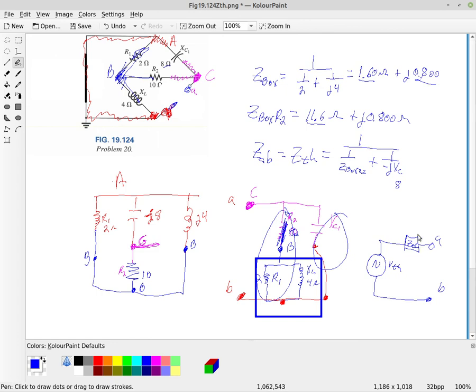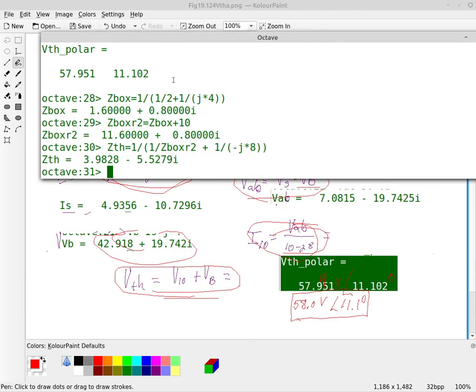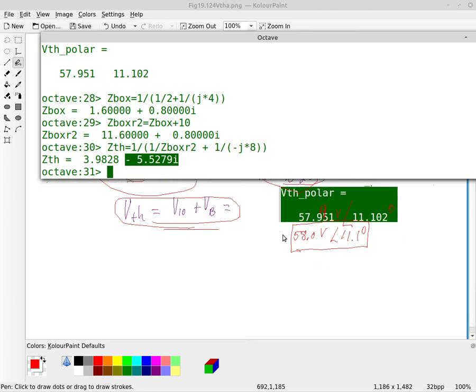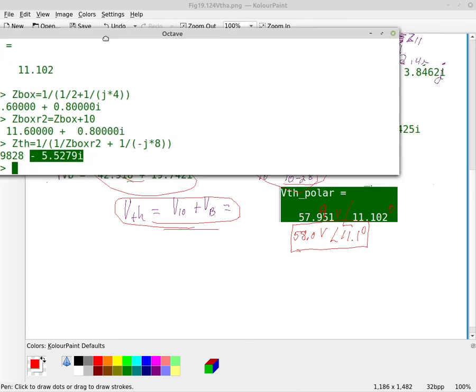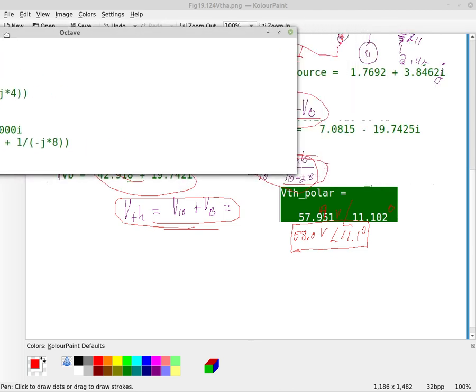All right, but in this box, I know there's a capacitor and a resistor, because when you look at these Thevenin values, you know that the real value is resistance, and then this is a negative sign, so that's obviously a capacitor. And so we could come back over here and draw this now.